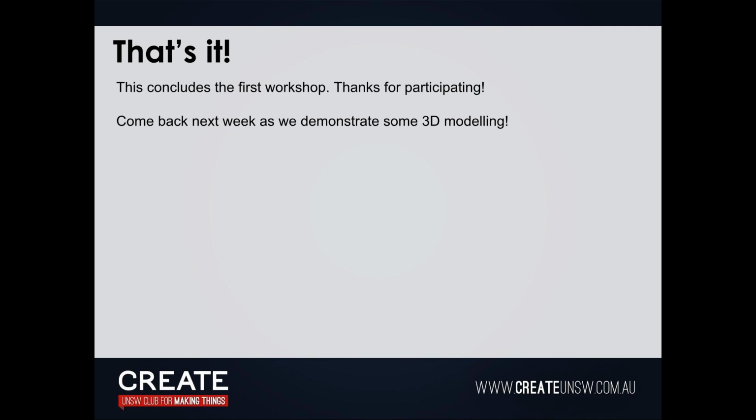If you don't care, if it's just 2 parts interacting with each other that you've modeled and they're on the same 3D printer, it won't really matter too much, because they shrink at the same rate. So if you account for tolerancing, it should be completely fine. And in my experience, those don't print too nicely. So you're going to have to sand it down a little bit if you want something really smooth. Yep.